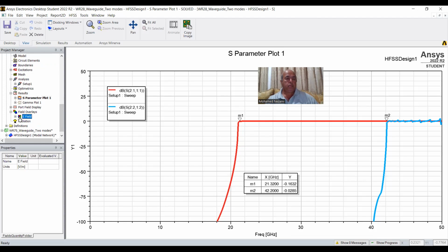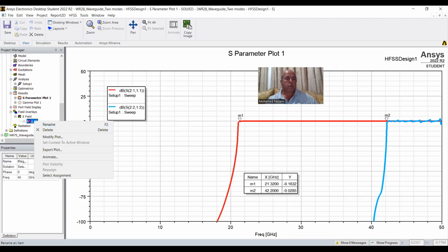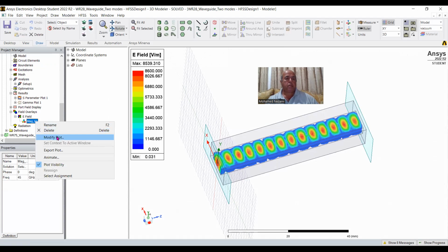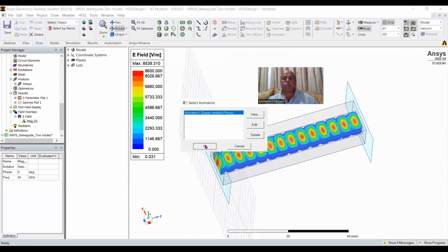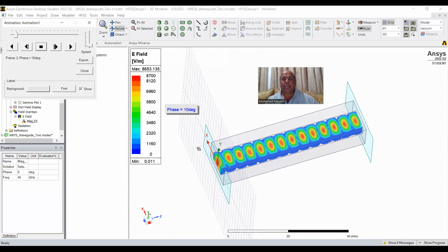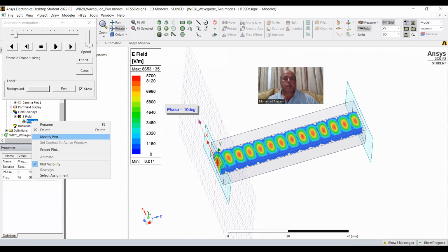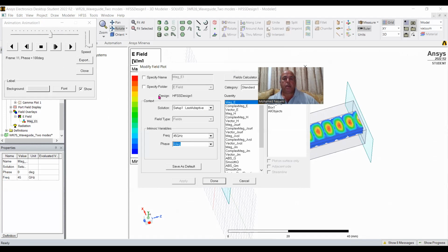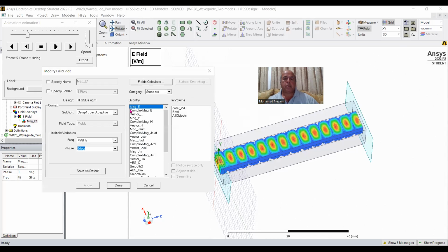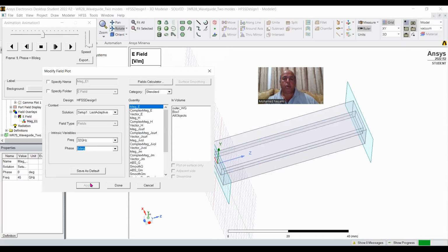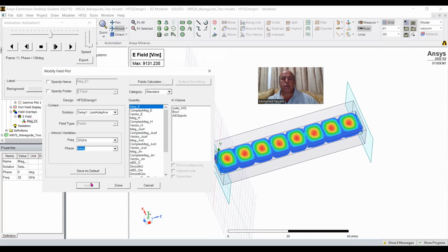And so let's just demonstrate. This is the E field. And let's just animate this for a moment, just for fun. Okay, so we can see that this right here is at 45 gigahertz. Okay, that's past the TE20. So let me back it a little bit into the 32 gigahertz. So this is 32 gigahertz, okay? TE10 mode, okay?